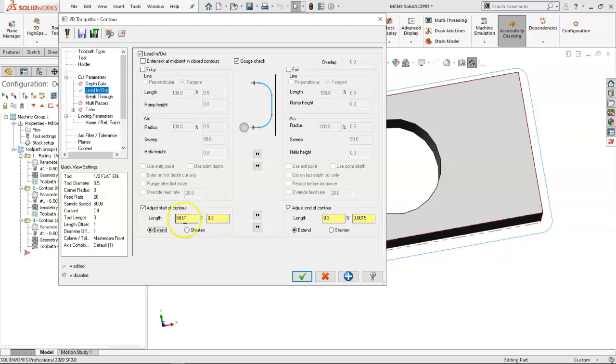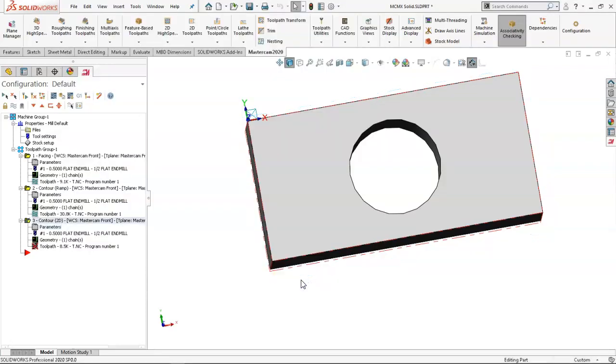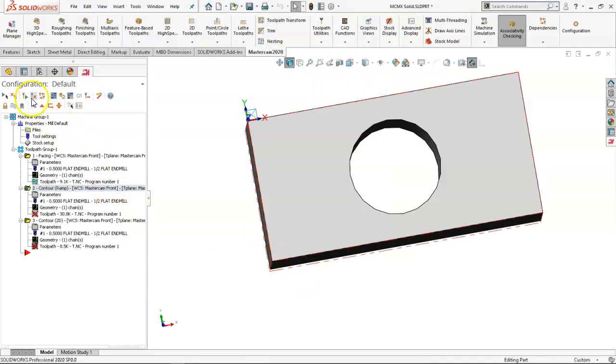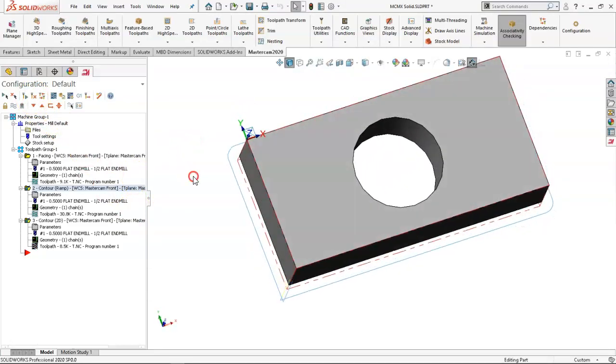So easy to make a mistake, but you know, it comes back to, again, being able to read those toolpaths and make decisions as you go. And if I did it on one, I can guarantee I did it on the other one because I did not go back and check it. All right, so those are the things you have to check and catch while you're going through the programming phase.